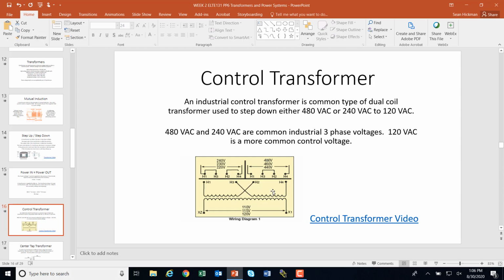Going back to the start of this, when we were reviewing, we talked about how when you put loads in series, you get more resistance and less current. So once we jumper right here, we're going to get less current through here, and that allows me to step that down from 4 to 1.